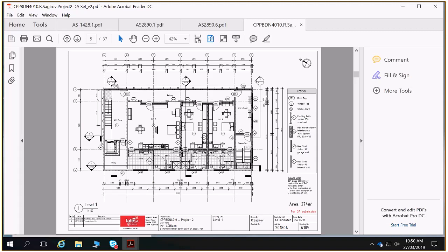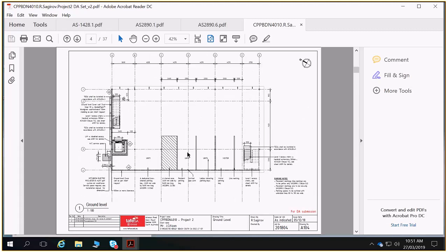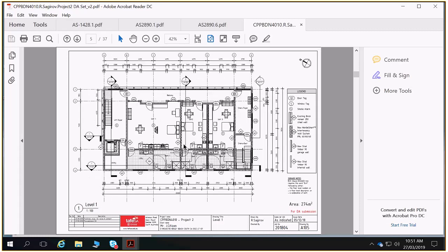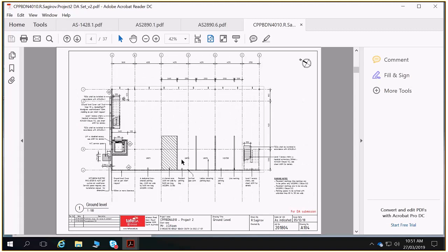If we are going to be messing with these walls, taking out these walls, that will require the installation of a fairly sizable lintel through there, probably a universal beam or so, to be able to transfer loads to where we've got columns. Beware that if you are going to be doing that sort of thing, if you're messing around with that wall in this central apartment there, so we've got these two units here like that, then it's not only your